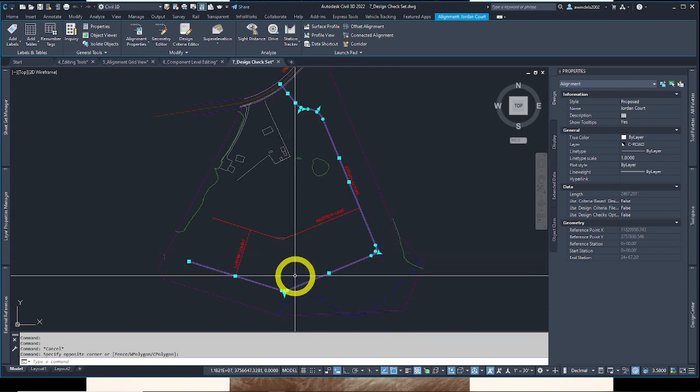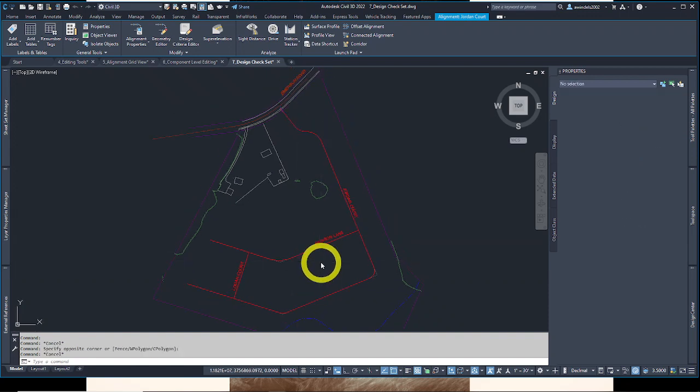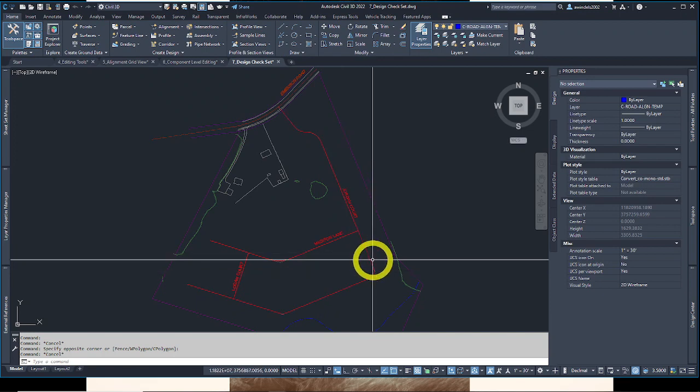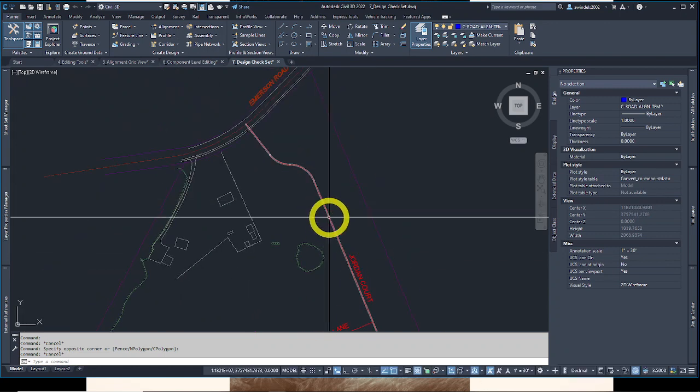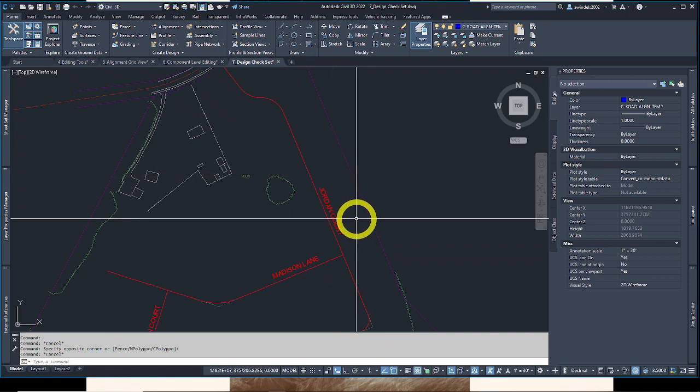Can you have curves go back to back without any tangent in between? Various things. What's the speed? There's a lot of entities that enforce, well, maybe enforce is not the right word, that give the design guidelines of these to be followed. It could be the state you live in the United States, its Department of Transportation, aka DOT. It could be a county planning commission, in my case, Missoula County, Montana. I've done many roads for them. They have their specific standards which rely on other higher up standards, and they default sometimes to the state DOT for certain things, for roads that interact.